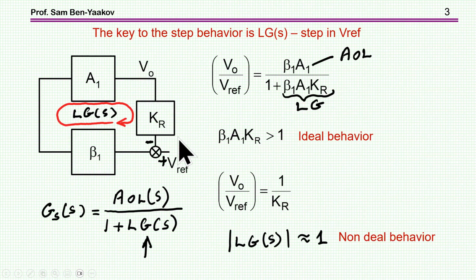Now, a feedback system, and I'm showing here a generic representation of a PWM converter. Here we have the phase compensator, the power stage, and this is the voltage divider. Here's the reference, this is the summing point, and since this is a closed loop system with negative feedback, we know that this is the relationship for the transfer function between the reference and the output.